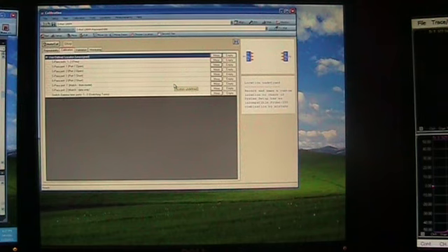Okay, so we have the cables hooked up to the probes. The tuner is in the initialized position, but it is in line presently. And we're going to do an on-wafer calibration. Now, this can be performed by any means you would like. There's certainly opportunity within the Agilent PNA's own CalKit system to perform this. If you have TRL standards and a TRL CalKit that would allow you to do this there, that's perfectly fine. I'm using WinCal. We're comfortable with it.